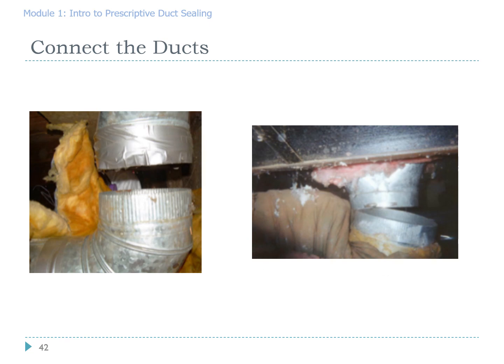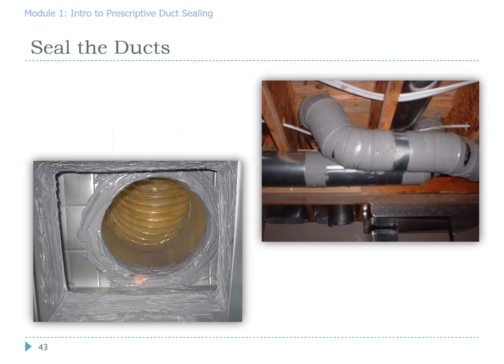Before applying mastic, you must connect the ductwork. You must put at least 3 screws in each sheet metal to sheet metal connection in order for the mastic to form a durable seal. After the system is mechanically fastened, it is important to apply mastic. It must be thick as a nickel. If you apply it too thin, it's not going to work.